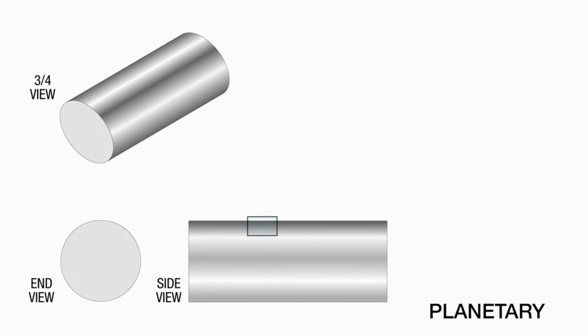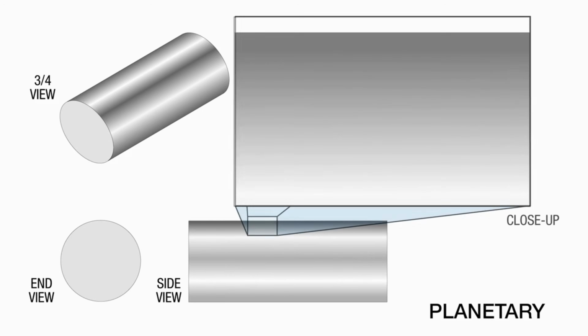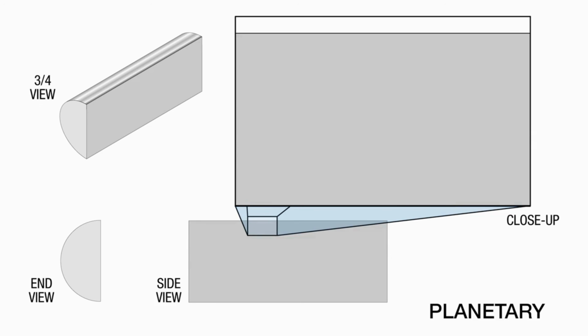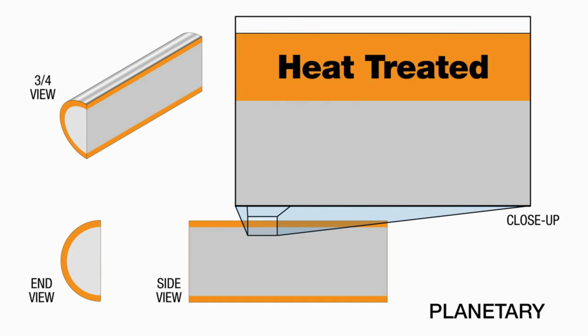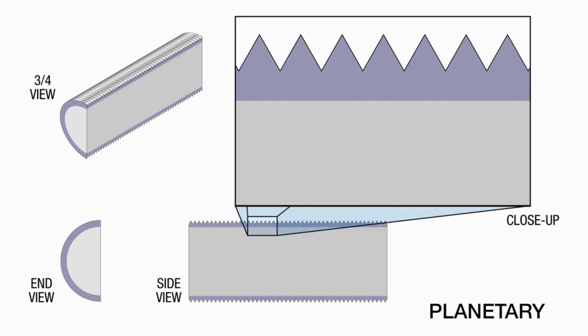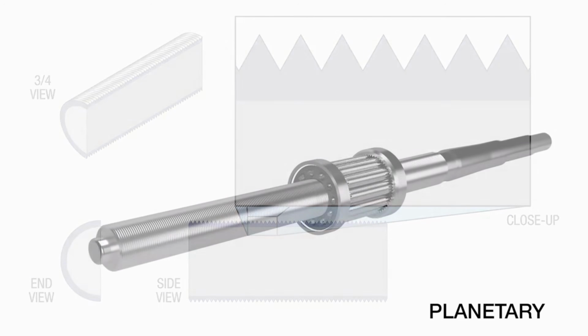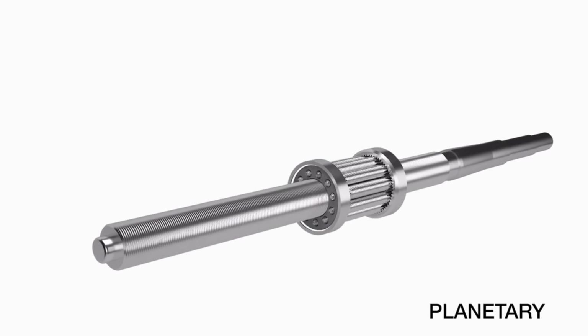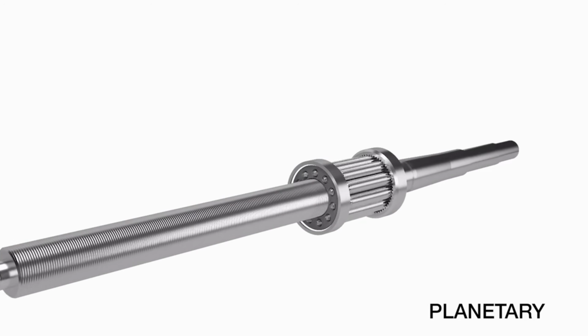Tolomatic manufactures the planetary roller screw design, where first the metal is hardened through a heat treatment process before machining the threads. The hardening process changes the microstructure of the material to increase its strength and hardness to a specified depth that is greater than the eventual depth of the threads. This process of significant heating and cooling the metal can distort machined features, which is why the planetary roller screw grooves are machined after the hardening.